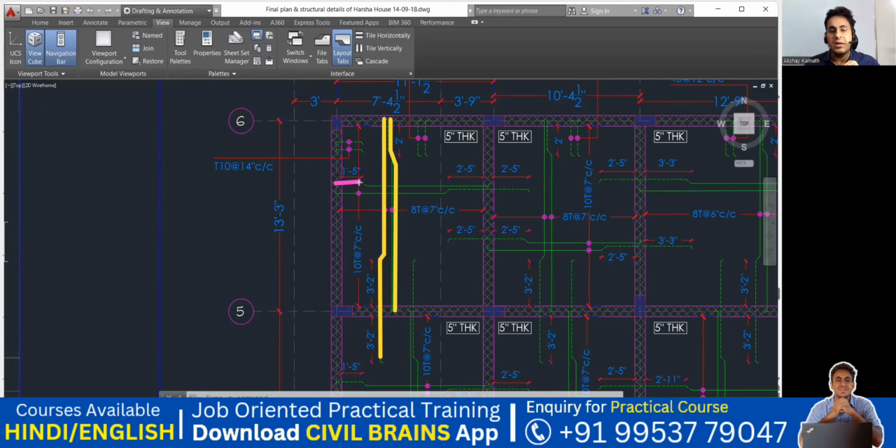See here, you have brought a crank, bent it here, took it like this. The next bar you are taking straight, you will give a crank here and you will take it here. This is my continuous support, right? So this will become my top reinforcement for this slab also. Got it? In this way you are supposed to understand the slab reinforcement. Slab reinforcement will take a bit of time. And now coming to the reinforcement details, what diameter you are supposed to use is mentioned.